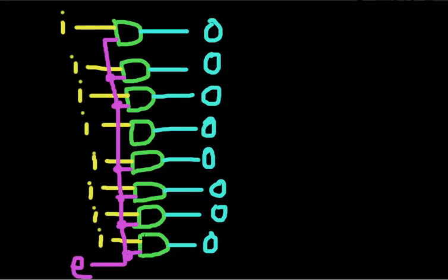It will go through to this one and then it will still go to this one, and as these are bits, they will only have one state, and all of the same state will go through each of these AND logic gates through these parallel wires. So it will all be the same. If this E bit is 0, then all of them will be 0, and this AND gate will produce a 0.